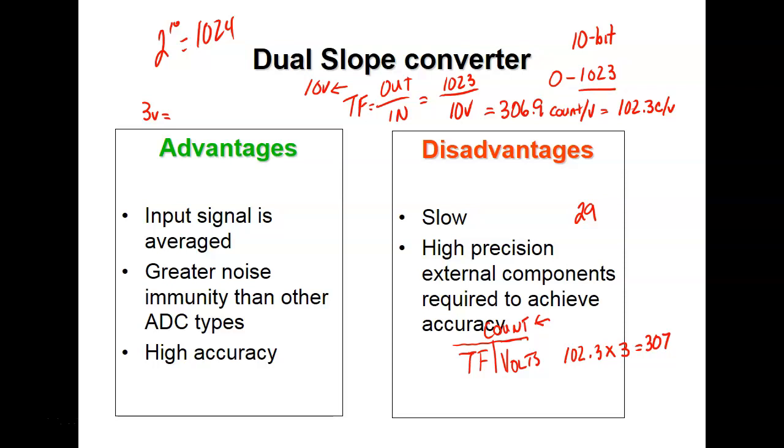Well, yeah. What you do is you take your maximum count out. Our maximum number we can get out is 1,023. We get 1,024 combinations, but the maximum count we get out is 1,023. Why? Because 0 is one of your counts. But you'll find out on 1,023 and 1,024, it's not going to make that much difference, right? You'd get the same answer. Go ahead, Brian.